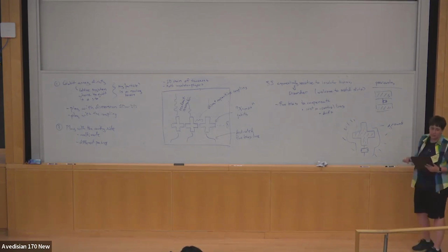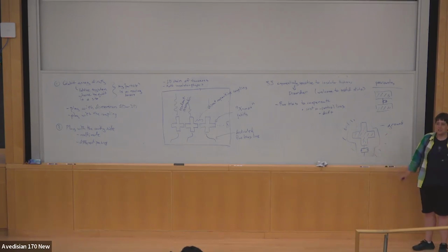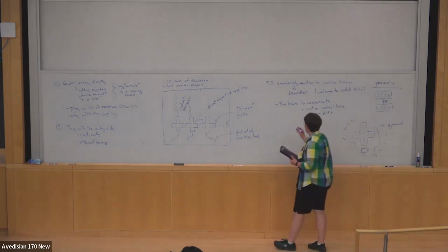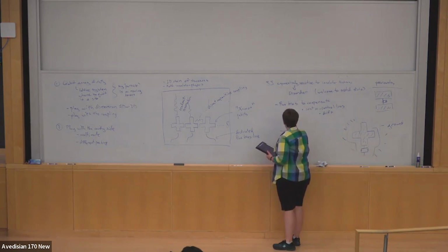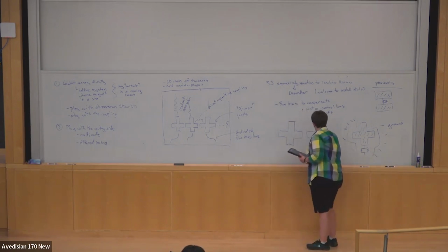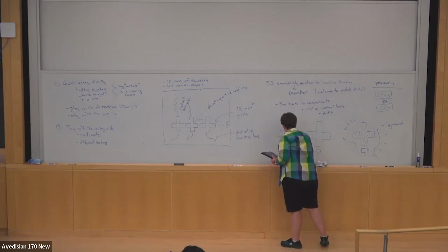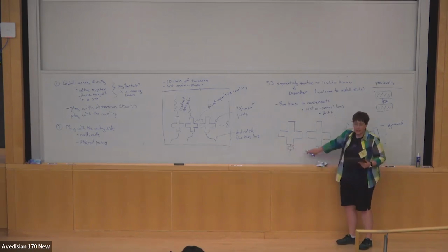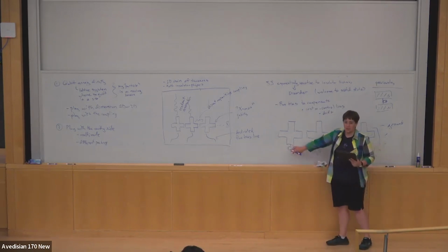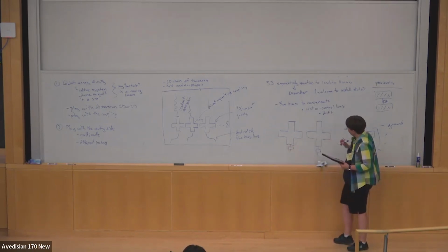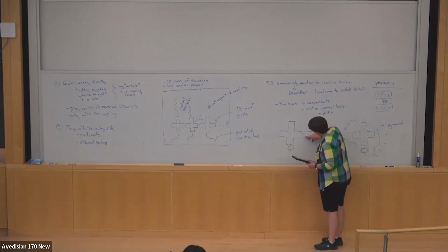And the nice thing about XMON is it has tentacles. And you can use the different arms for different things. And so, like, if you have a 2-qubit XMON device, like this, so this end is the flux bias end. That's where I thread magnetic field. That's where I control the frequency. If I want these qubits to interact strongly, then I can bring these two very close together with a big area.